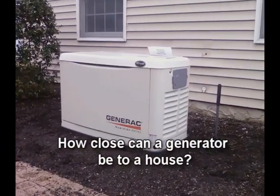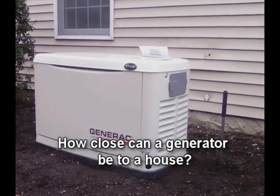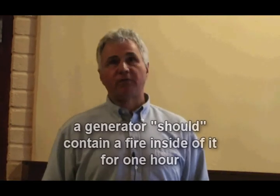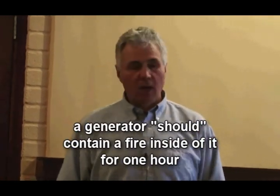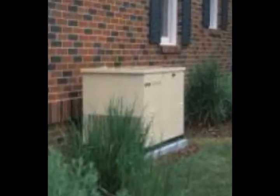How close should the generator set be to the home? Well, that's a 1 hour fire rule. In other words, if the generator set can contain a fire for 1 hour, you can put it right up against the house. Will the generator set manufacturer tell you the rating of their enclosure? No. So then you're stuck. There's a quandary there. So if the generator set is up against a non-combustible wall, like a brick wall, see brick here? Not a problem. Could it be a foot away? That's not a problem. Most town inspectors will not give you a headache.